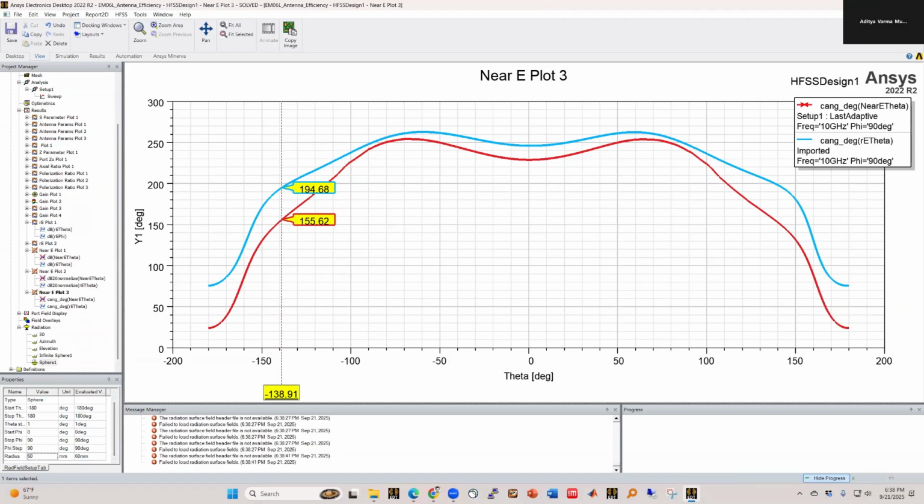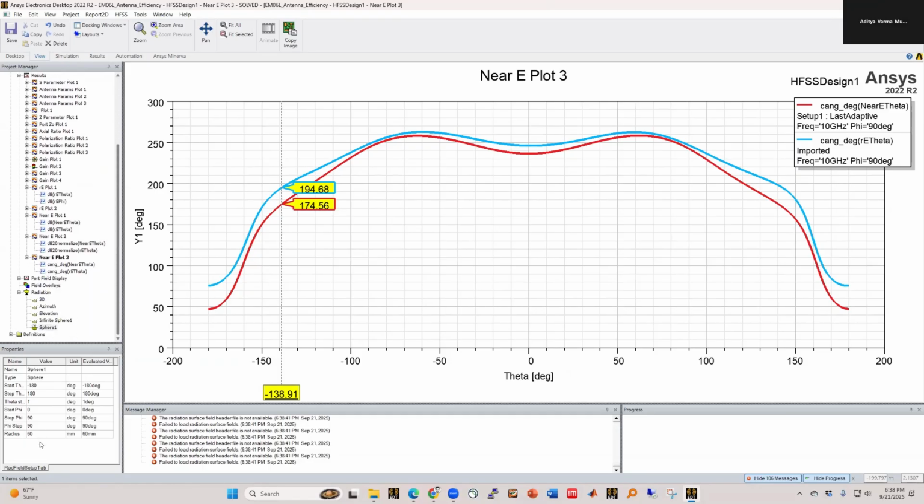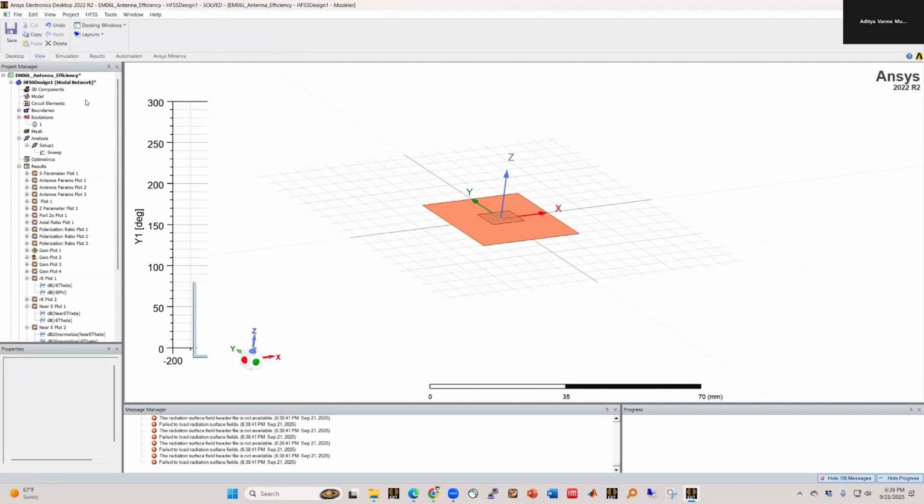If you're at 60 millimeters, then that phase error becomes smaller, right? So now the phase error is like 20 degrees, which is less than 22.5, right? So the answer is kind of, we'll see next actually, that the far field distance, which we calculate as 2D squared over lambda, what should D be, right?